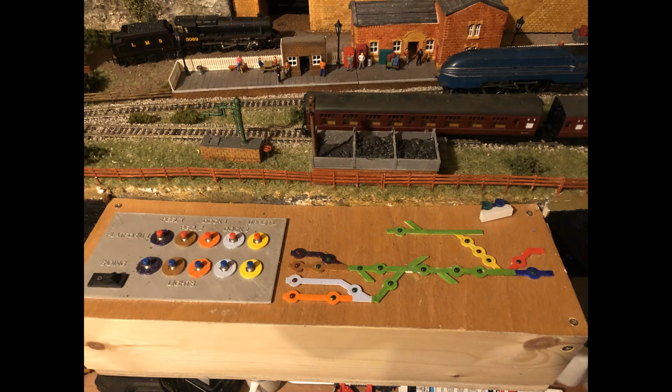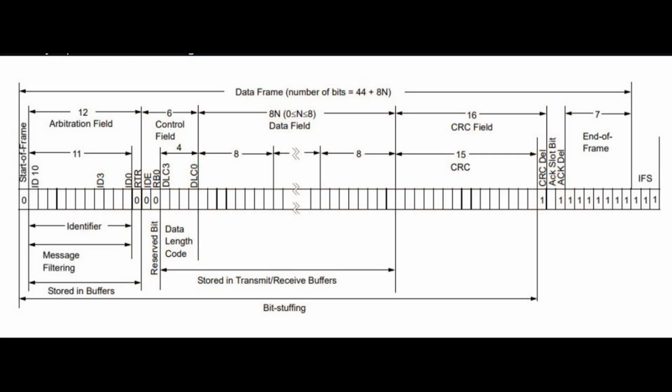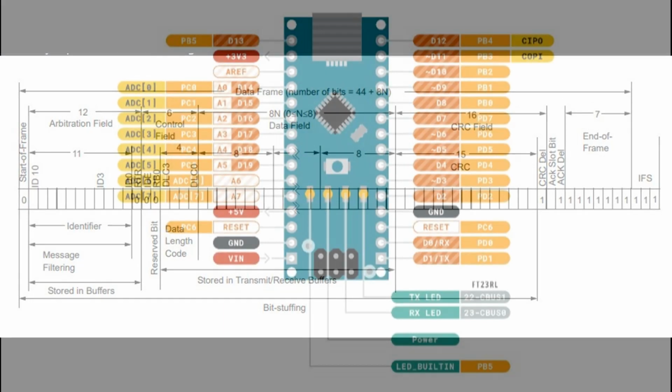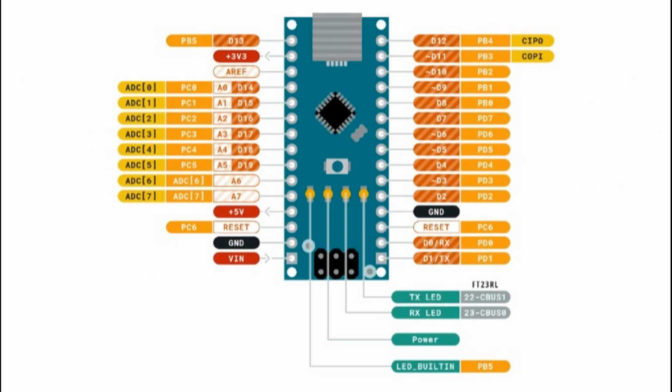This particular Arduino Nano will function as a producer node with a designated high priority on the bus. To achieve this, I've assigned it a CAN ID of 001. Among the Nano's pins, A6 and A7 are exclusively reserved for analog input, but for this project, we'll focus on the digital capabilities, utilizing pins set to either 1 or 0. Additionally, pins 0 and 1 serve the dual purpose of being the RX and TX for USB communication. In this setup, we'll be concentrating solely on the simple digital side of these pins.